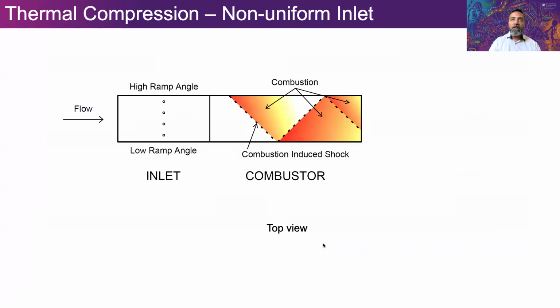The other thing we've been doing, this is my colleague Tristan Vanier's work. He's looking at thermal compression. So you remember you have that inlet that does the compression for you. What if you don't have a symmetric inlet? You have different ramp angles. And what if you try to produce high thermal compression that can lead to ignition, particularly of the fuels that don't want to burn easily? So that's a body of work he's done before.